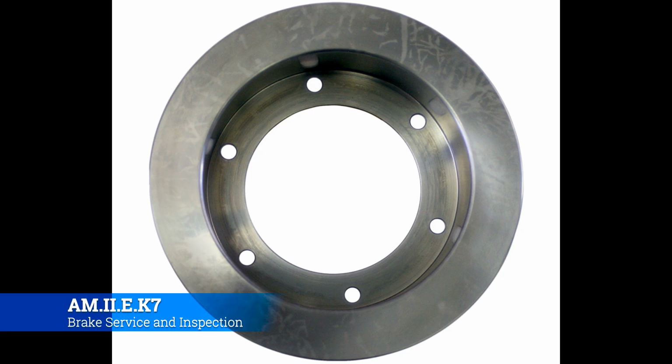Okay, so aircraft brake discs. Once you get them pulled off, you're going to want to make sure that you've inspected them mainly for cracks, but also any kind of gouges, any sort of corrosion. Now, granted, these are iron, and they're going to get exposed to heat, and they're going to get exposed to a lot of friction, so you're going to see some oxidation on there. That's fine. Basically, the first time that you touch the brakes whenever you're going down the runway, it's going to take care of most of that corrosion.